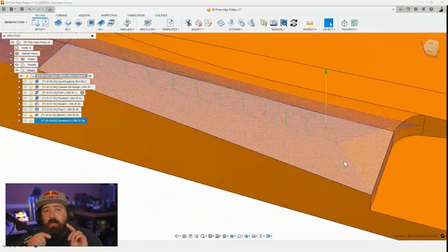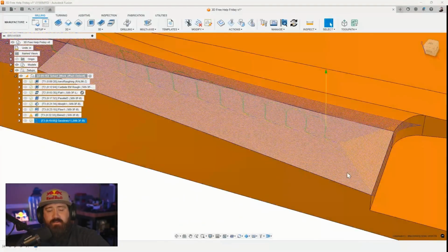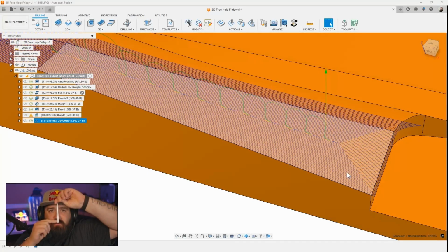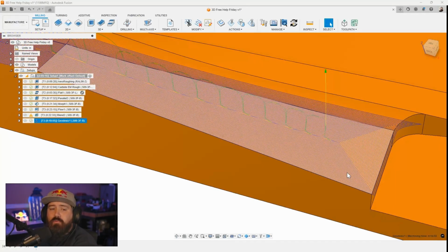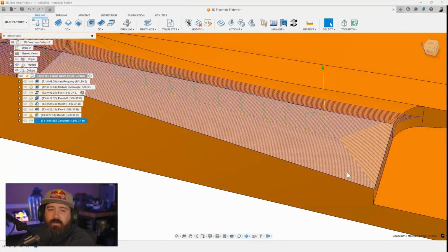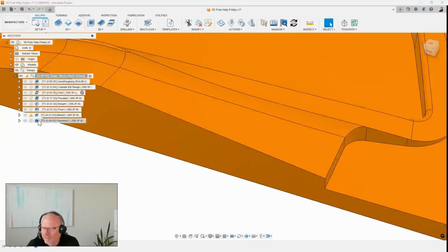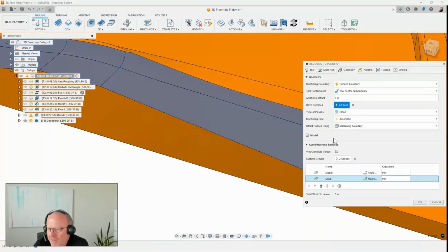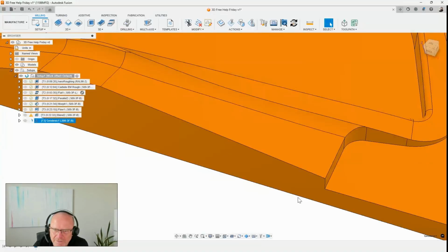That's going to result in differing tool pressure. If you have, let's say this tweezers is my tool here. If you're cutting and you're supplying constant pressure to the tool like this, and then you snap the tool the other way and change the direction, the pressure is not going to stay consistent on the tool, right? So every time you change direction, your tool is kind of doing this a little bit. That's why you're going to get those marks on your part. So we want to be very smooth and steady with our direction here. We call that coining. Coining, like if you take a coin and press it in sand or something. And then also there's the offset passes, but you're going to get to that later.